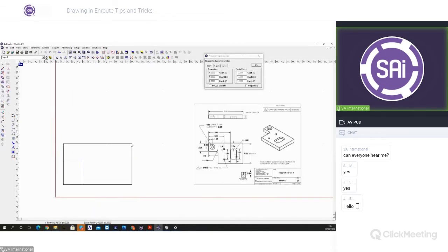So then we could select both of them. So first this one, and then the one that we'd like to subtract from it. And we could weld subtract to get this shape. Or alternatively, we could simply use the jigsaw weld tool and just drag out this shape from there.